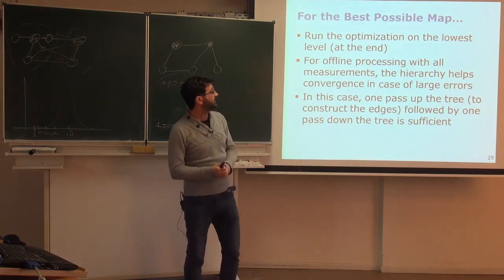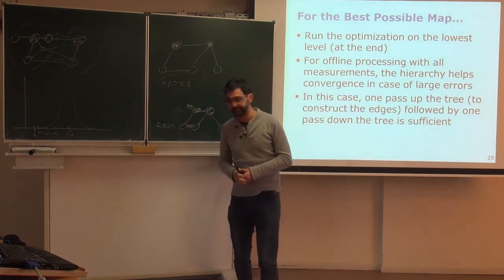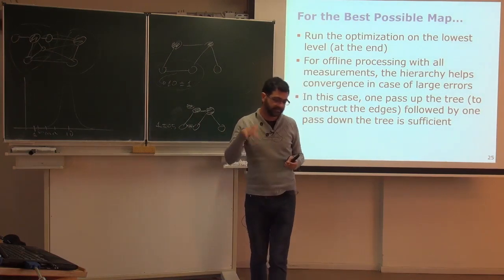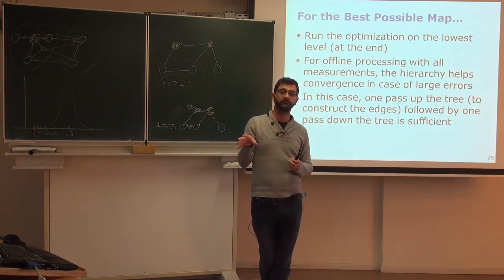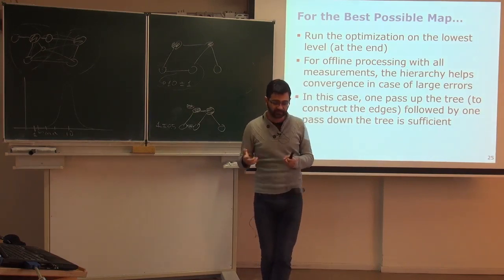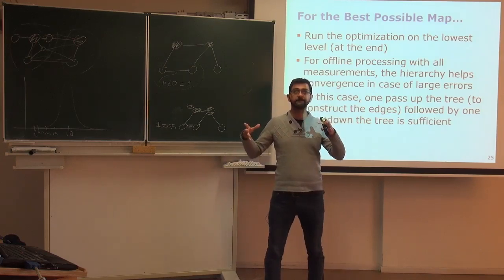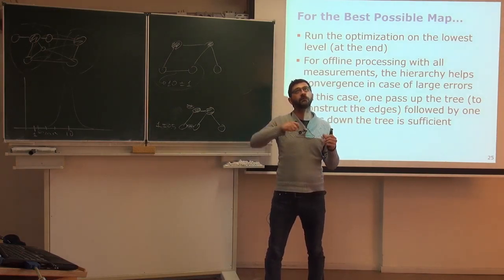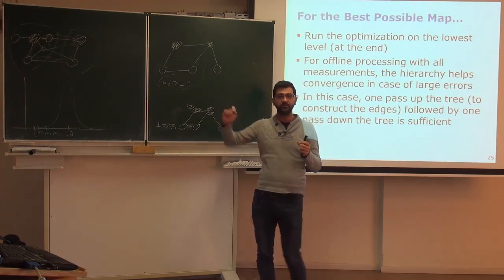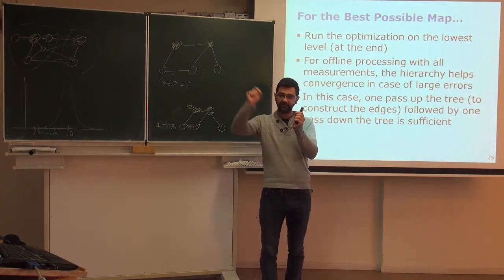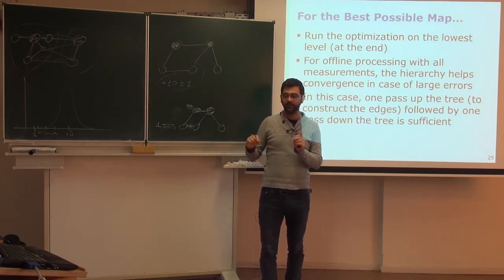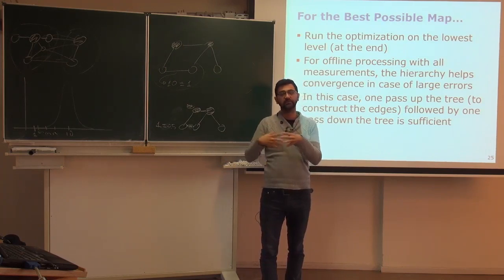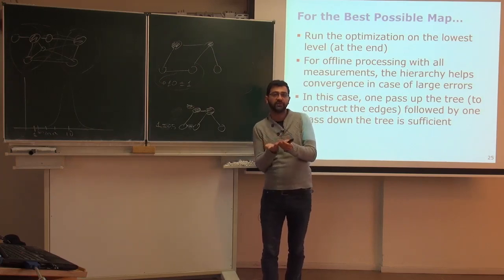The second thing is actually not written in here, and it is quite interesting. It can happen that you get better maps because you end up in a better minimum, okay? The reason is that when you have too much data, you get a very shaky cost function. Each of these measurements adds a small peak in your cost function, or, if you see it the other way around, a small minimum. And when you eliminate some of these measurements without destroying the whole topological structure, you remove some of them that do not make too much sense.